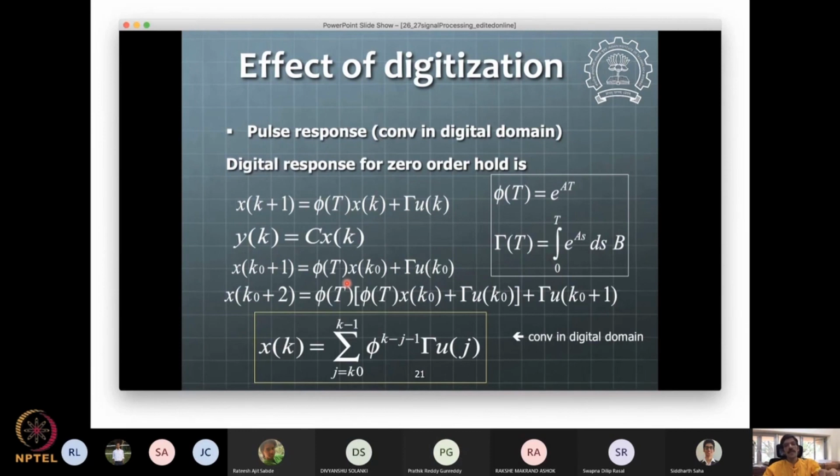But whenever you feel that you must use a lesser sampling time, then you may need to trigger the digital domain analysis of the system to make sure that your designs are not getting any worse performance. So one can think in the digital domain itself and design controllers in this domain to make sure that your system will work even if your sampling is a little less.